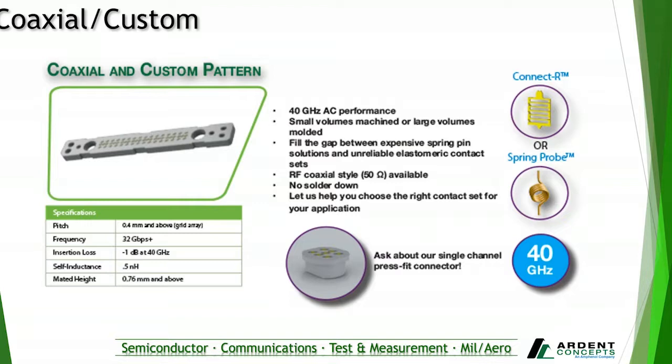Again, this can utilize either our connector contact set or a spring probe contact set with performance out to 40 gigahertz. And we do have a note here as well to ask about our single channel press fit connector system. We can utilize just a single coaxial channel, what we call a puck, to create a quick press fit connector system.